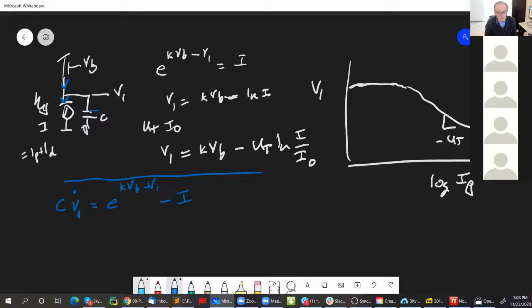Now, that's the large signal differential equation in dimensionless units. What we usually want to do is go small signal and express this around some operating point. The way you do that is you say the nodes have a particular conductance, a linearized conductance around some DC operating point. You can do that quite easily here. You just say, what's the derivative of this current with respect to V1? That's the conductance. The VB is constant, right? The easiest way to do it is just to write it out. After a while, you just do it automatically.